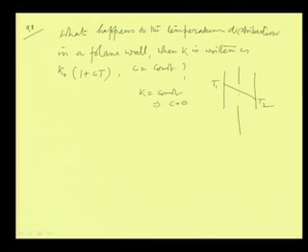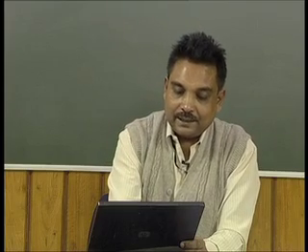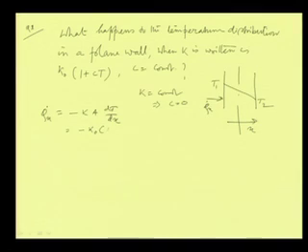We know from Fourier's first law that Q dot X is equal to minus K into A into dT by dx, because we are considering one dimensional heat transfer. Here K will be replaced by K naught into 1 plus C T. That means minus K naught into 1 plus C into T into area into dT by dx.